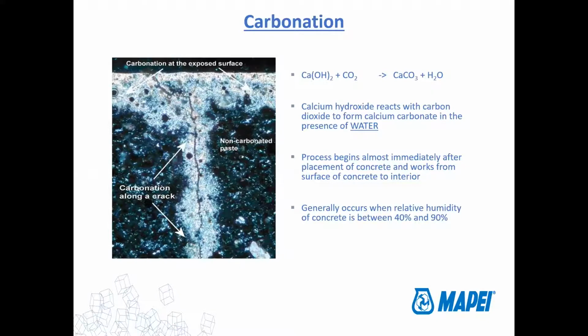However, the calcium hydroxide does react with the carbon dioxide, and you get that calcium carbonate in the presence of water. So you have to have wet concrete. If you're in a really dry, arid environment, Las Vegas, Arizona, somewhere like that, this process doesn't actually happen because it's just so dry. But it does begin pretty much immediately after the placement of concrete when the conditions are right. Those conditions do include a relative humidity between about 40% and 90%, which is pretty typical for most areas outside of, like I said, Las Vegas, Arizona, some of the drier, more arid environments.